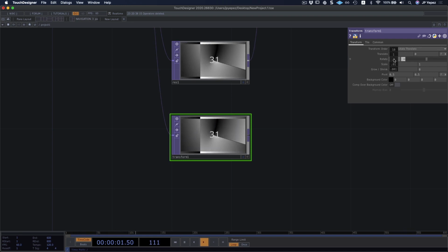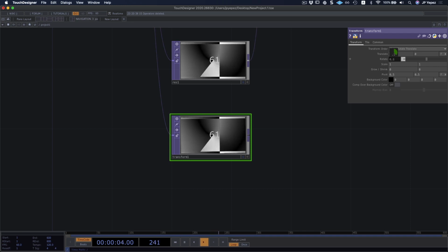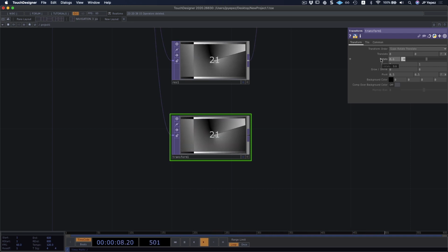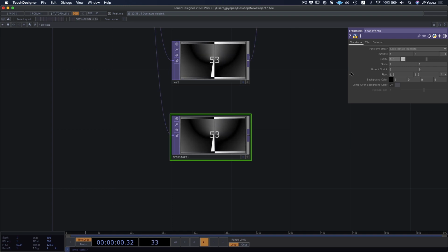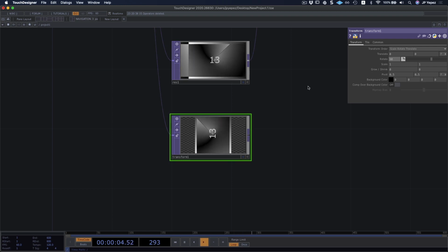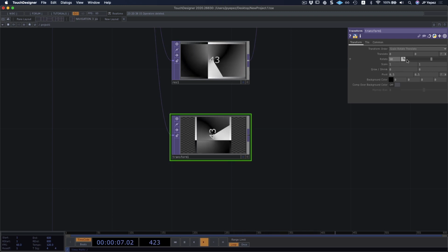You can also rotate your image. You can see that small increments don't really do much. Remember that whenever you perform rotations at a node level or with your components, you're talking about degrees. So unless you do something like a 90-degree rotation, you're not going to see much.